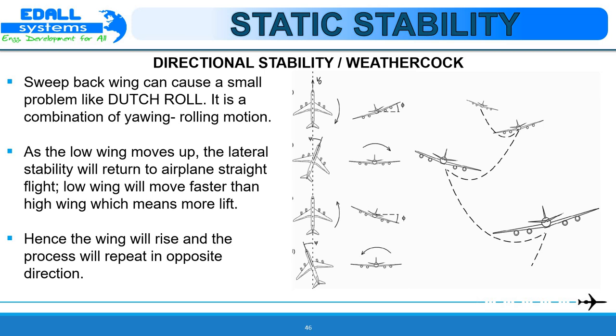Since the moments of inertia in pitch and yaw are of similar magnitude, the frequencies of the Dutch roll mode and the longitudinal short period mode are of similar order. However, the fin is generally less effective than the tail plane as a damper, and the damping of the Dutch roll mode is often inadequate. The Dutch roll mode is also called so because the motion of the aeroplane following its excitation is said to resemble the rhythmical flowing motion of a Dutch skater on a frozen canal.